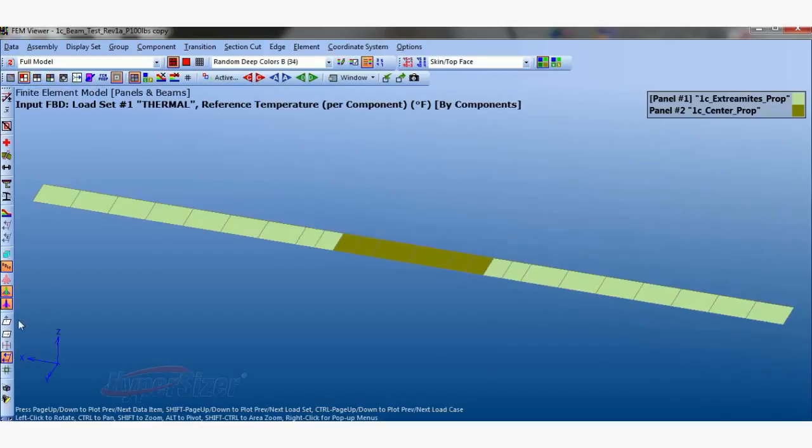So 2 things you must check before we do the analysis. X direction. We always like the X to be span-wise, so we know what NX is. If this is inconsistent or it points the opposite direction, you have to understand those parameters. It's always best to have X in the span-wise direction.